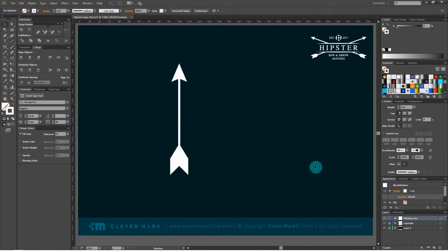As you see, the size of the top and end of the arrow is not quite suitable for our needs. Now I will set the size below the menu. You need to express in % how much you want in relation to the original. I will select 60% for the top of the arrow. For the end of the arrow, select 50%. Now it looks much better.